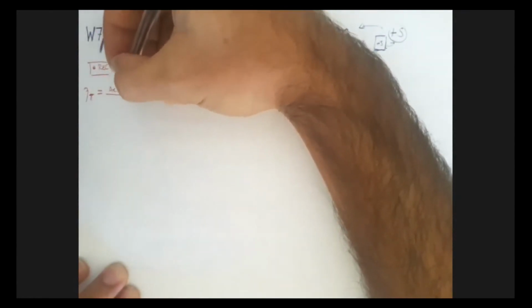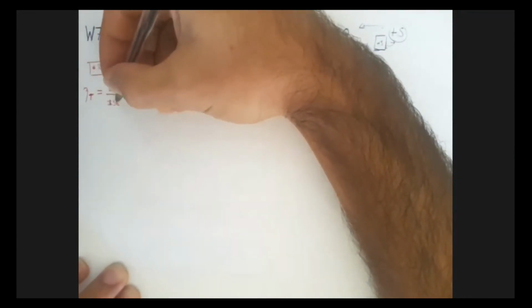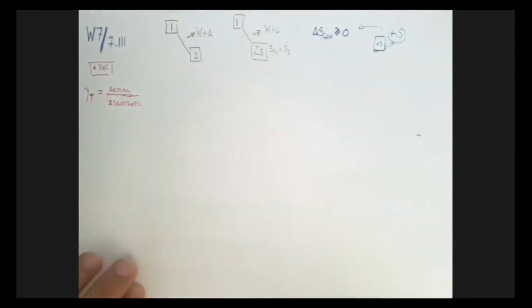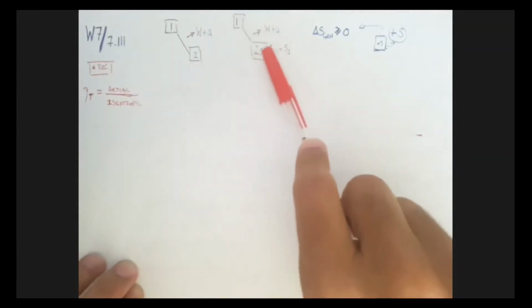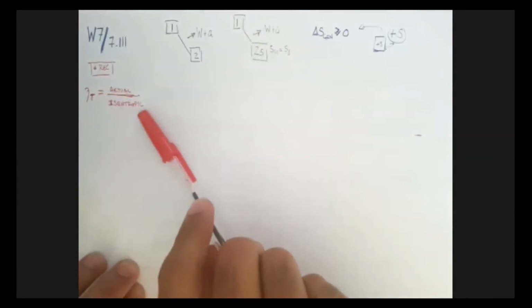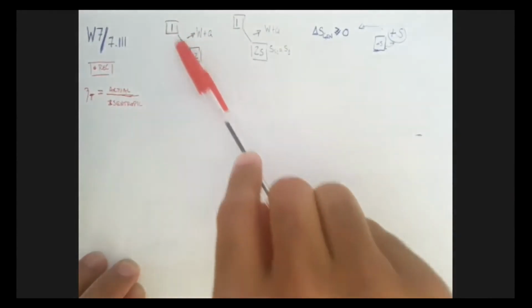So it's a measurement of how much actual useful work I can get over how much I could possibly get in the isentropic system. Think of it as an ideal system. If I do an ideal process from 1 to 2s, all with reversible processes, I would have a certain amount of energy. But since I have some irreversibilities, right?